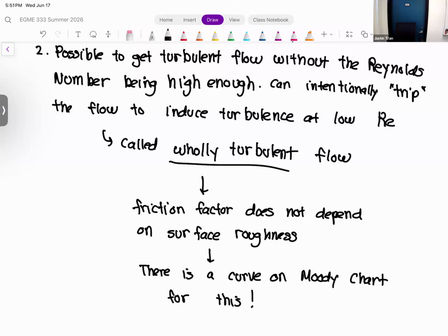Those dimples are basically intentionally tripping, or manipulating, the turbulence, because a golf ball is flying through the air at very high speeds. To help the ball travel further with less drag, it helps to have the boundary layer stay attached to the ball as much as possible. And the dimples kind of help with that.